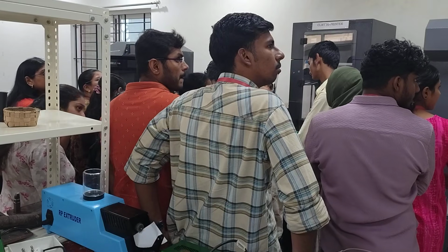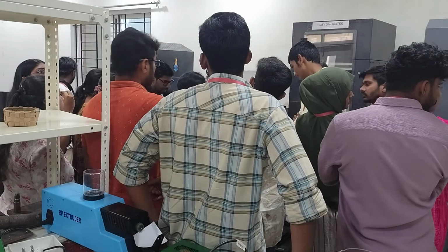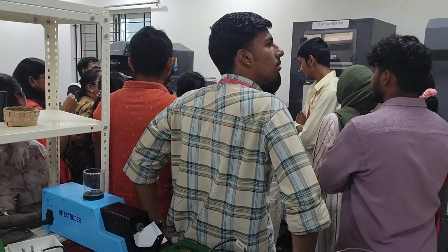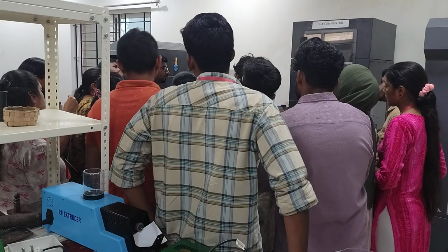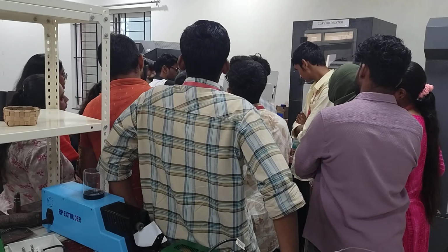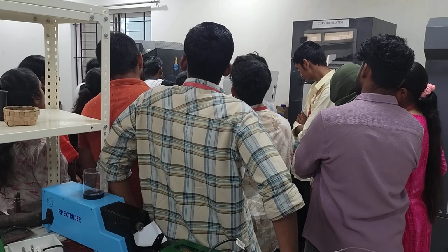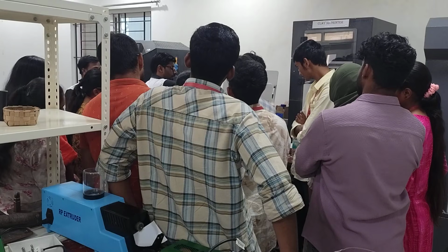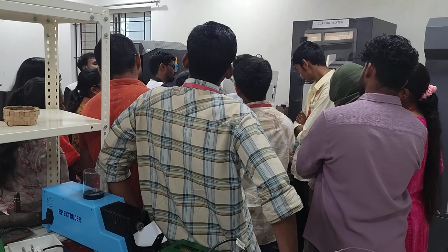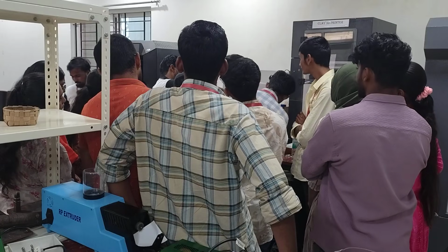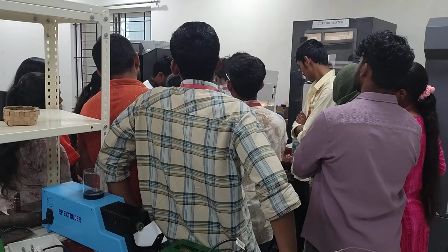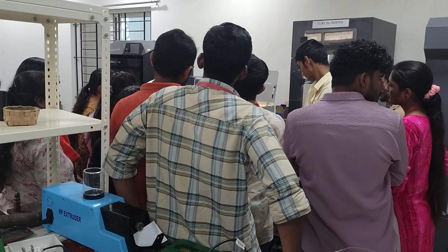Cut the filament from the inlet side of the extruder and remove the bowden tube from the outlet. So filament from the inlet side of the extruder. So this is our extruder. Okay, I'll just remove it. We had a cutter. This is a screw. I just unscrew it. Then I'll click on next. Wait a second, one more thing I'll do.